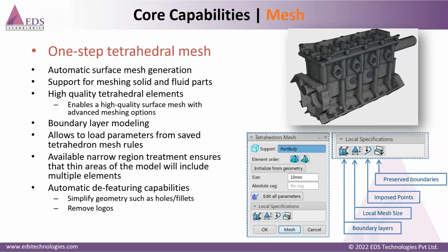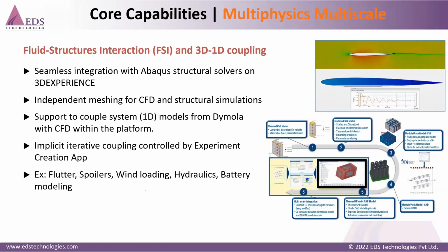And automatic defeaturing capabilities are available here, wherein with a click of a button, you can simplify geometry. If there are any holes, you can fill the holes. If there are any fillets, you can defeature or defillet them. If logos are there, logos can be removed, all through a simple click of a button.